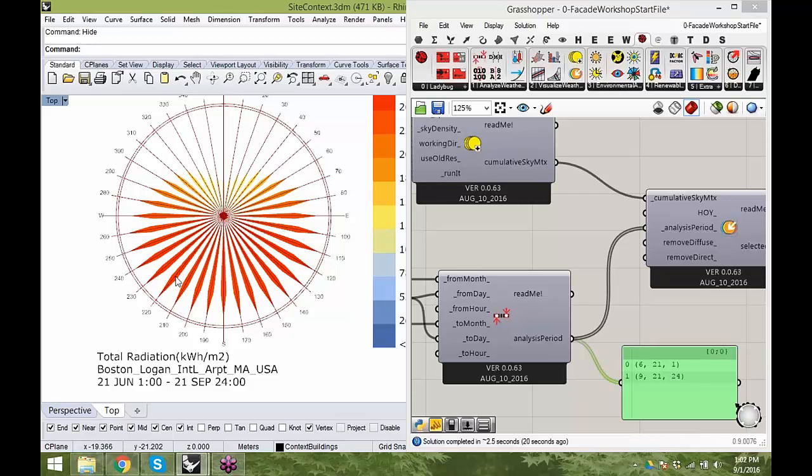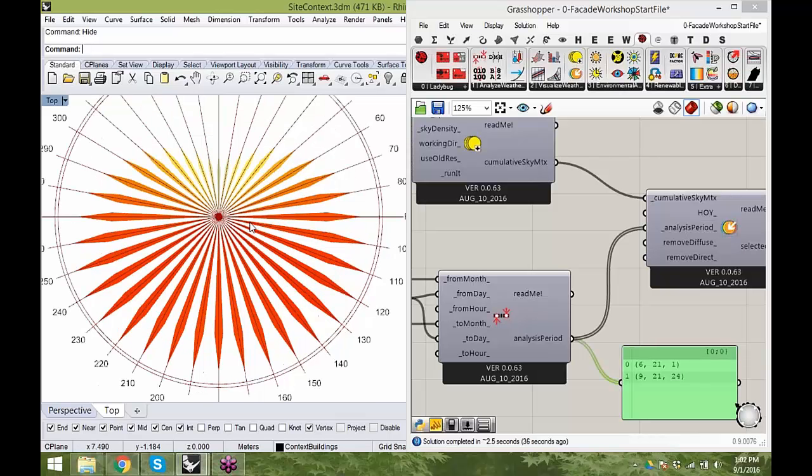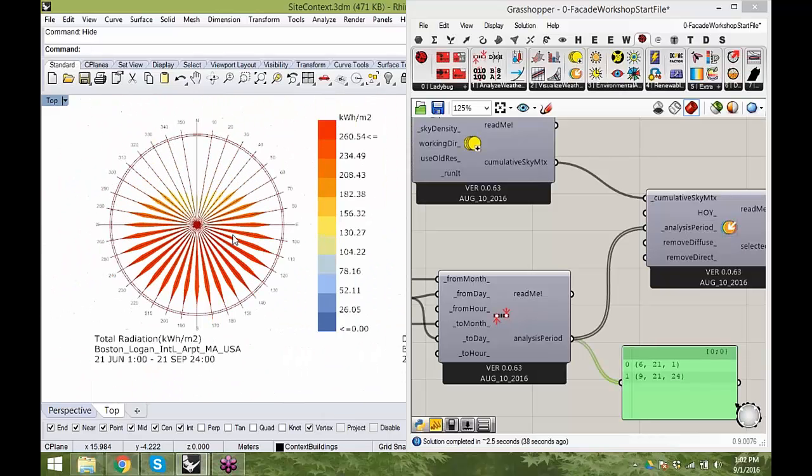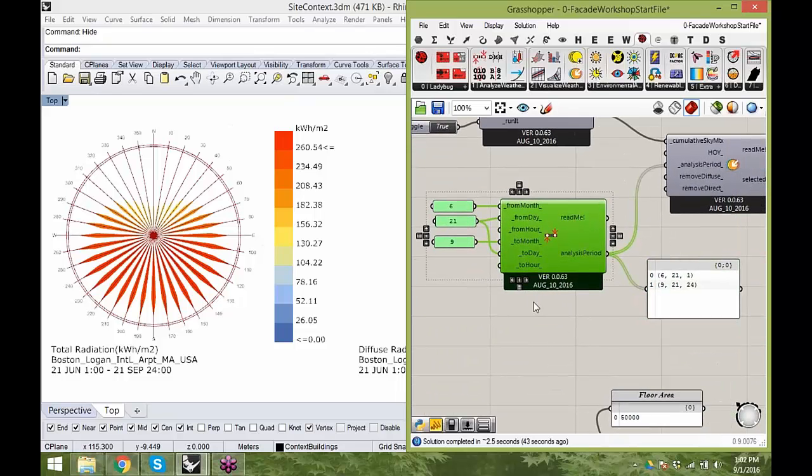And it's actually, I mean, it comes more intensely from the south than the others. But I guess if we really want to try and minimize this, probably the best way, because this is narrower than it is wider on each side, we probably want to orient our building north-south, essentially, in this type of situation. And we can do the same. Let's say that we're not necessarily interested in using the sun, we're trying to minimize the harm.